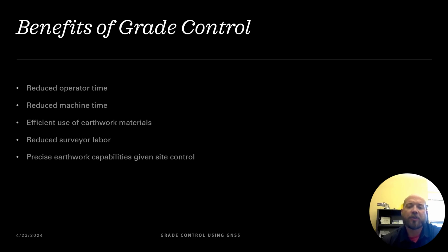And then you have reduced surveyor labor, because you just have a surveyor setting your control and then giving you your model to put into your grade control software. And it gives you precise earthwork capabilities given that site control.